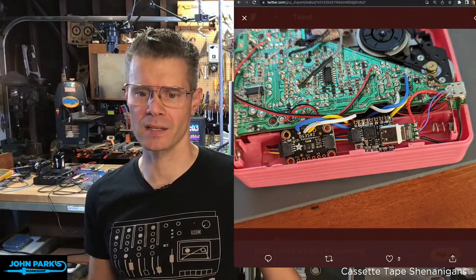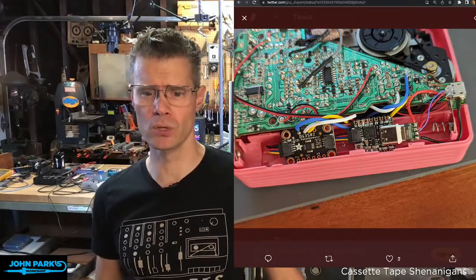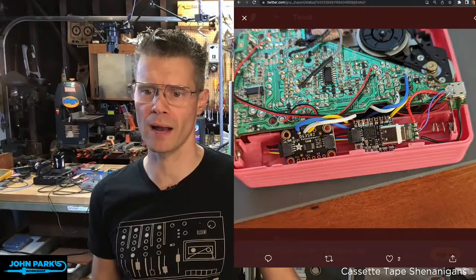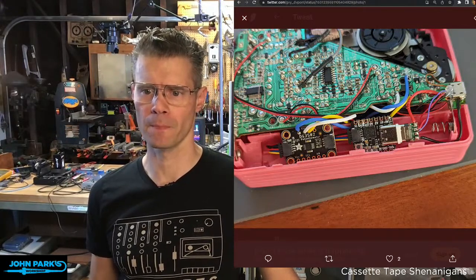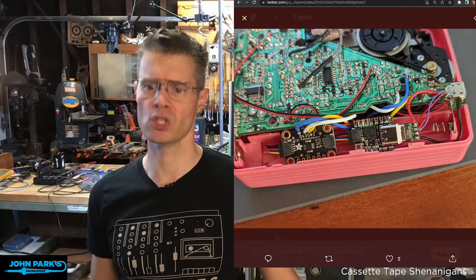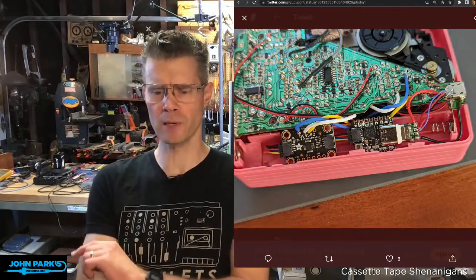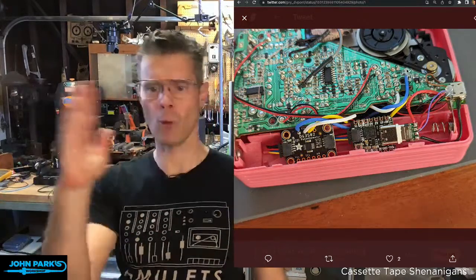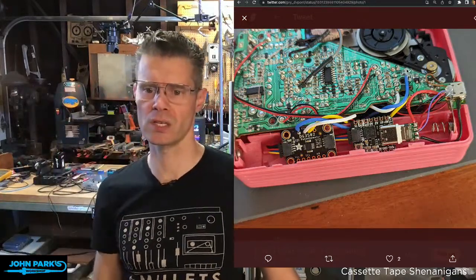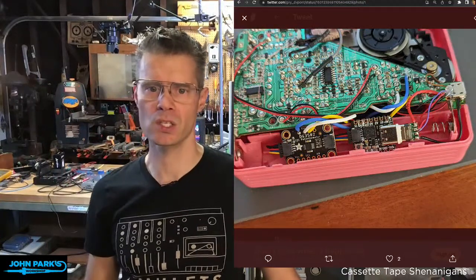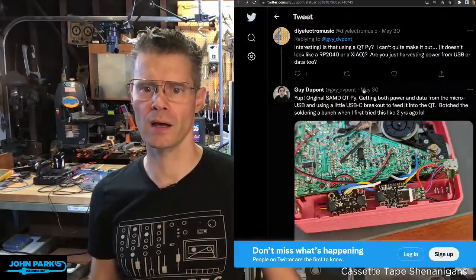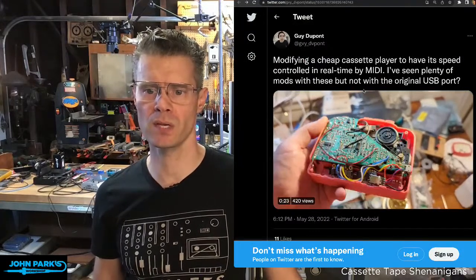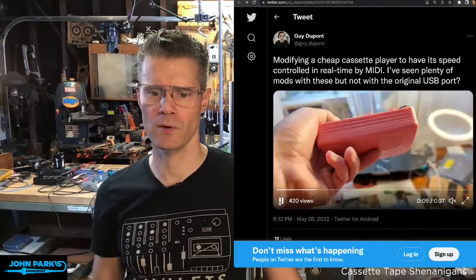And there's that Dallas Semiconductor 3502 I2C potentiometer, so that is connected up to those points, ground, and then the two, there's the wiper, ground, and voltage, I'm presuming. And then digitally changing that position of that wiper to adjust the motor speed. So you can check that out just on Twitter, Guy DuPont, GVY_DVPONT, has some info about that.